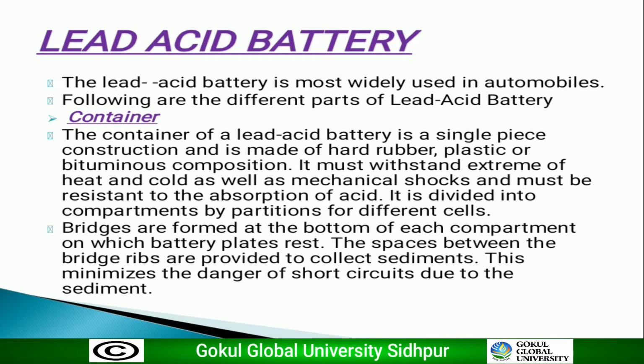This container is divided into compartments by partitions for different cells. In this container, bridges are formed at the bottom of each compartment on which the battery plates rest. The spaces between the bridge ribs are provided to collect sediments. These sediments I will discuss later. This minimizes the danger of short circuit due to the sediments.